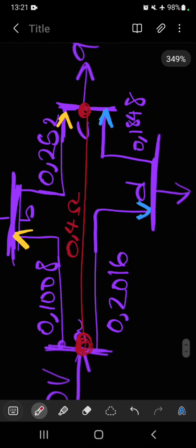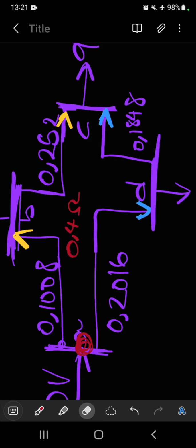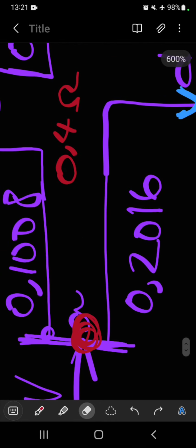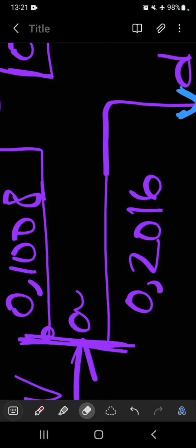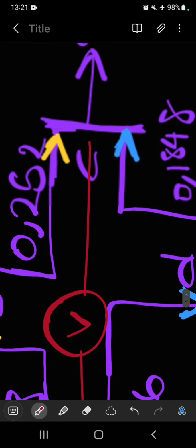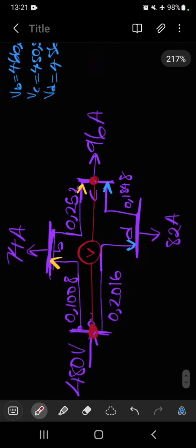So the first thing you're going to have to do is find the VThevenin. Remember from electrical 2, when we were calculating VThevenin, we would remove or pretend to remove the point that we're actually interested in. So that's why I'm removing the interconnector, just for the purpose of finding the VThevenin. Instead, we're going to place our voltmeter there.